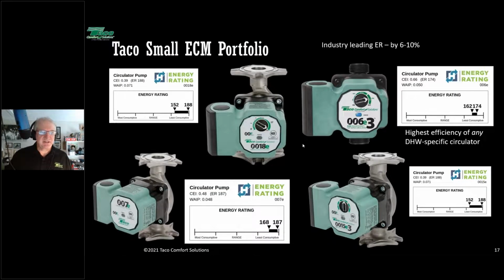Just a couple things, some of our DHW circulators and their energy ratings in terms of efficiency, our ECM circulators and their energy ratings. We have 3 stainless steel models here for small residential applications. The 007E, which is 1 setting. The 0015E3, which has 3 settings: 5-foot head constant pressure, 10-foot head constant pressure, and full speed, fixed speed. Both of these are really good candidates for oversizing.